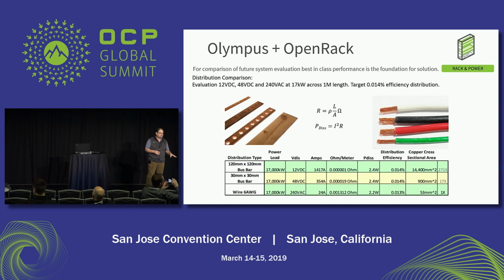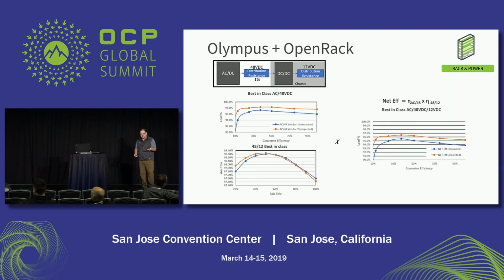That's the takeaway. I would venture to say that 48 volts is manageable. Copper's not that expensive. We can manage that cost if there's an efficiency advantage. And let's talk about efficiency. I think there's been tremendous breakthroughs in the topologies of 48 to 12 volts over the last 5 years. Prior to that, we were looking at fixed duty cycle converters, hovering around 96.6% efficiency. Very good, well thought out design.